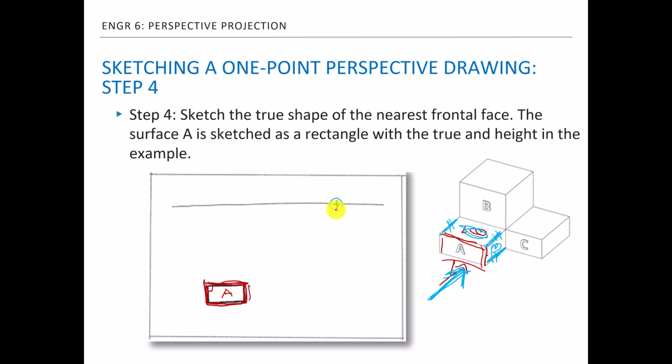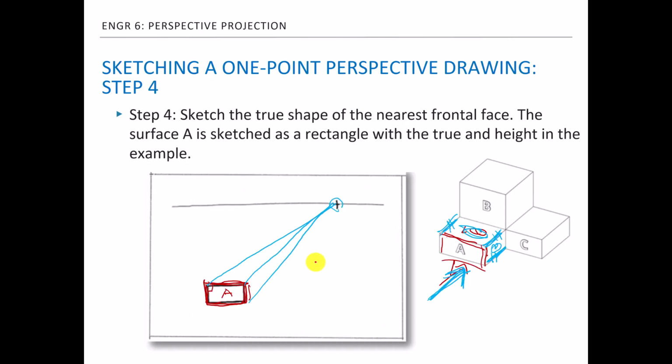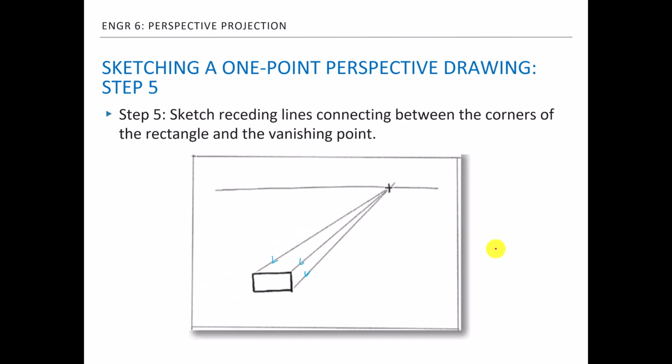Okay, so in order to draw these side lines, from the position, you just need to draw lines to the vanishing point. So that's why we sketch in here all these lines, those are the blue lines in the object there, right? And they are parallel to each other and they are parallel to my eye direction. So those are all lines that have to point and converge to that vanishing point.